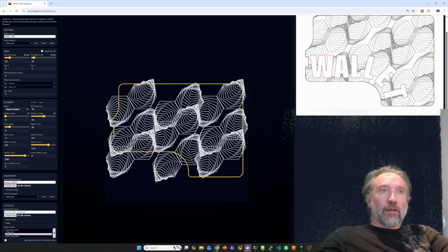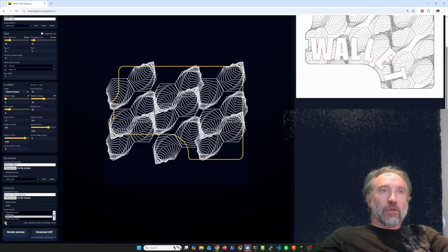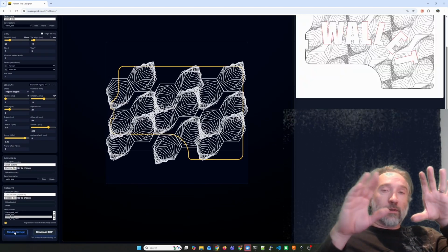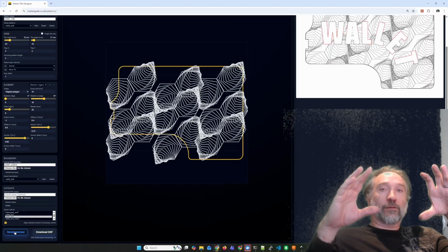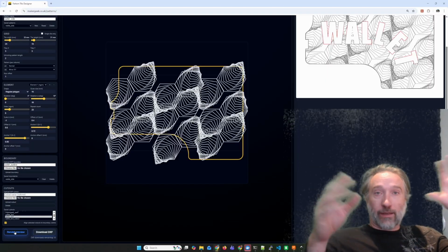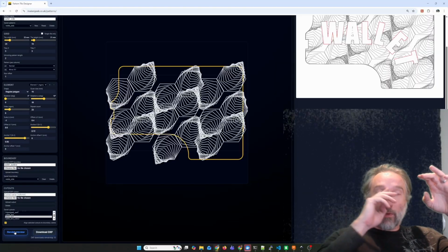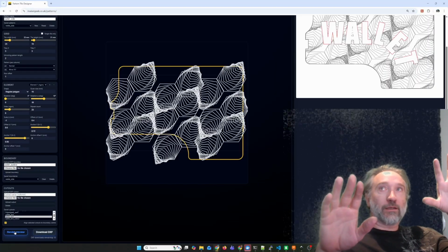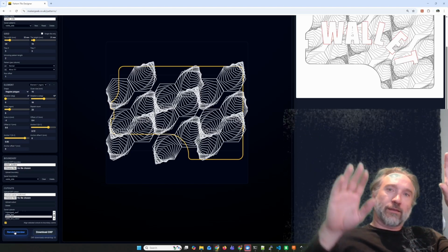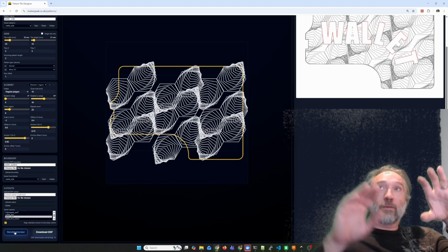I will comment, like earlier, I used this checkbox to center the pattern. Because I created these at the same time in Fusion, the exported DXF is in the same coordinate space, but you might not maintain that. There's all sorts of reasons why you might end up with ones that don't overlap each other. That's what happens when one is off weirdly compared to the other, or maybe not even visible at all.